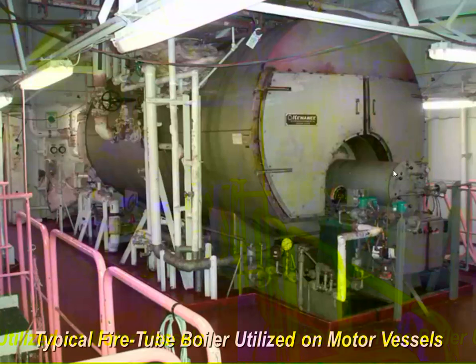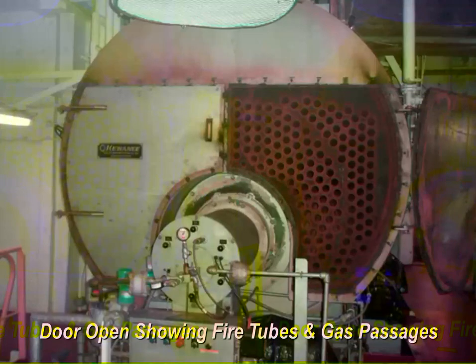Now, right here, this is your rotary cup atomizer, and combustion air is going to be coming through this tube. It will be mixing with fuel and burning in the combustion chamber. So this is just a picture of the door opened up for service, and you can see the generating tubes within this boiler.